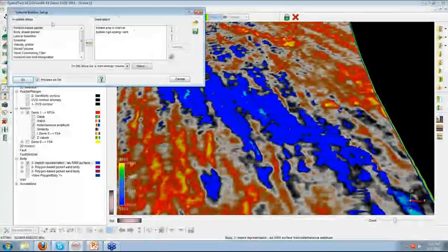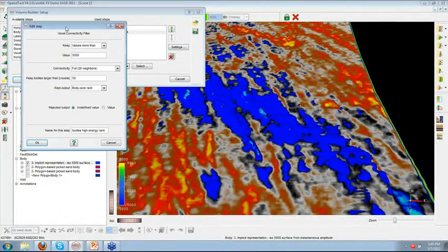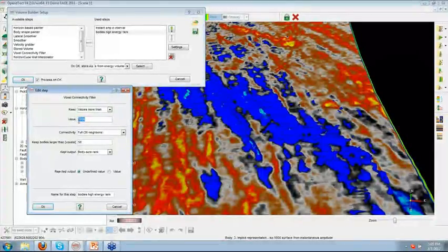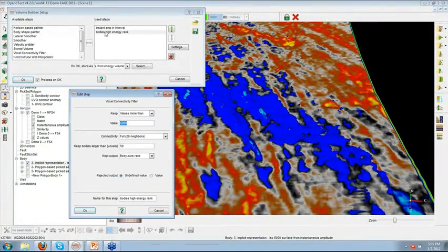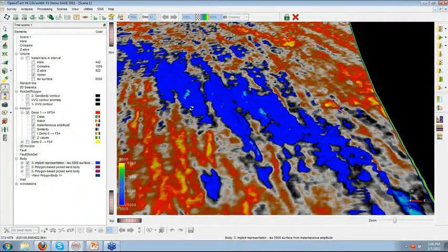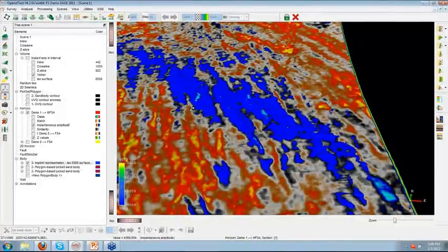And then the trimming using the voxel connectivity filter is also rather easy, because you will have set the threshold already. It is the same value. It's very likely that you will use the same value here as what you used when creating the other surface. And the trimming is very easy to test, because you can quickly apply this voxel connectivity filter a number of times in order to filter out the small bodies and leave in only the large interconnected bodies.